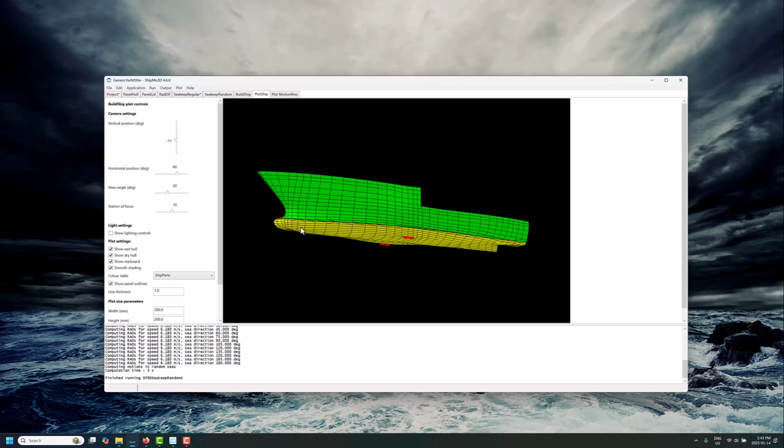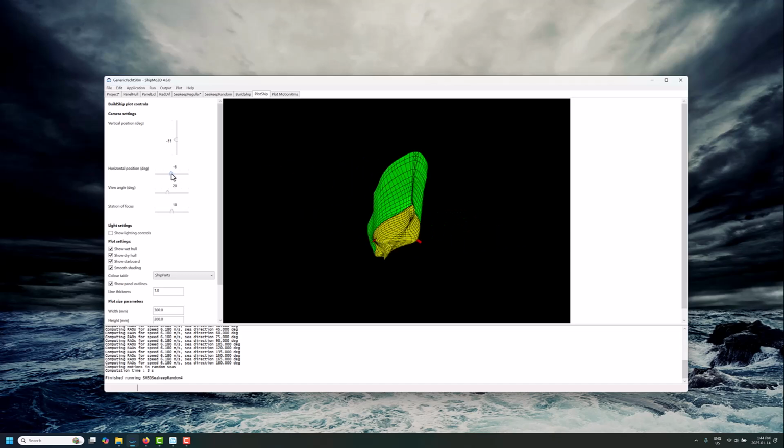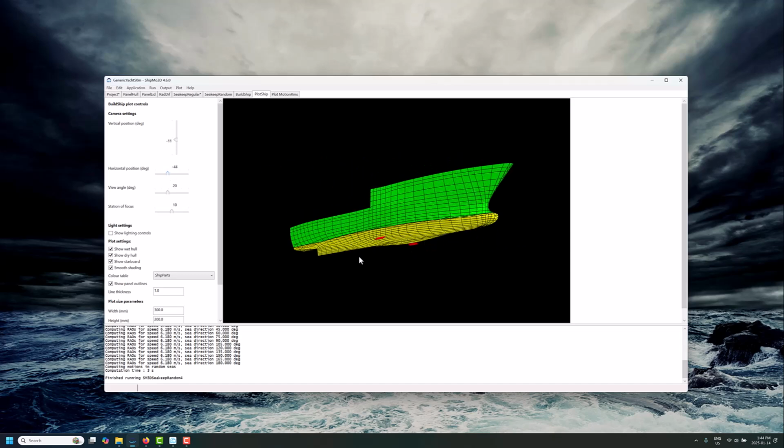The other thing to keep in mind is that there will be a coupling effect to other degrees of freedom, so if these fins are placed more towards the bow of the ship, that'll start to affect pitch motion as well. Really what I wanted to do is give a basis for what's happening behind the scenes in the hydrodynamics for the fin stabilizer model, to give an initial appreciation of the implications of using them. It's meant as a starting point, which I think will give you a lot of insight into what's possible, especially at the earliest stages of design.